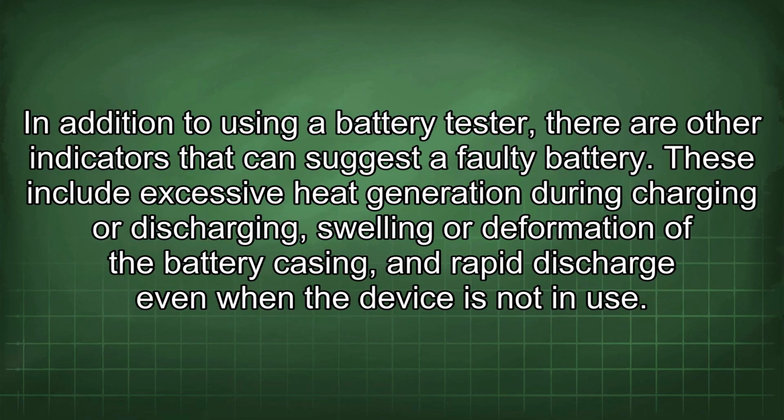In addition to using a battery tester, there are other indicators that can suggest a faulty battery. These include excessive heat generation during charging or discharging, swelling or deformation of the battery casing, and rapid discharge even when the device is not in use.